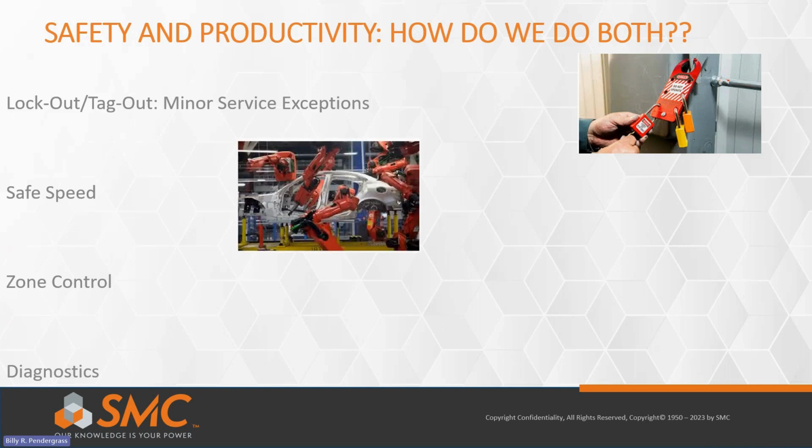What about safe speed? The machinery service functions such as cleaning can be dangerous if they're carried out when machinery is operating, but they also are time-consuming when machinery must be shut down. Because of this, plant floor personnel will too often find a workaround to a machinery safeguard and service the machinery while it's running in an effort to save time. This equals a recipe for disaster.